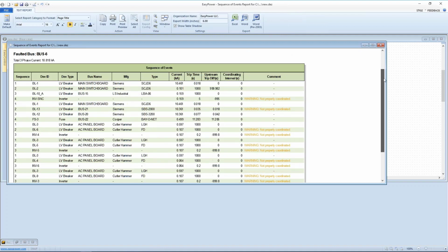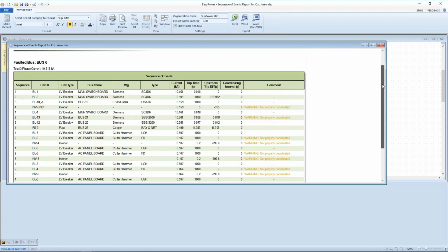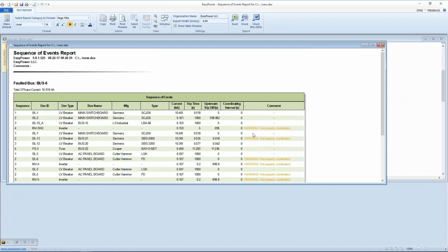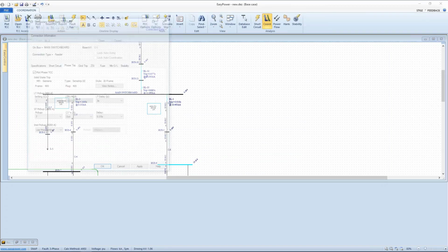This is just an example of how convoluted the issue becomes, and most of these DC protection or the remote protective devices really won't clear at all because they don't have enough current going through them. So that gives us some guidance in terms of how to set up the scenarios.